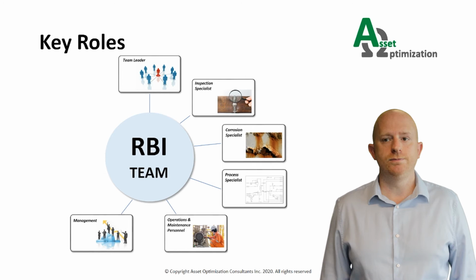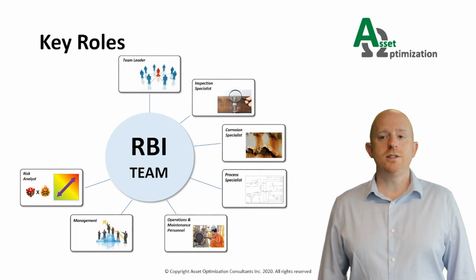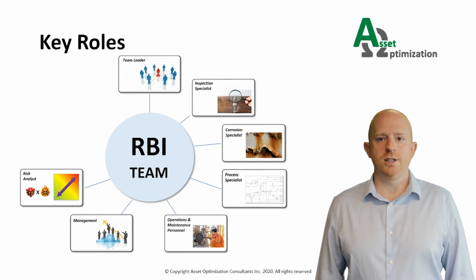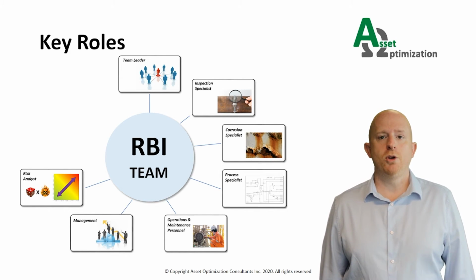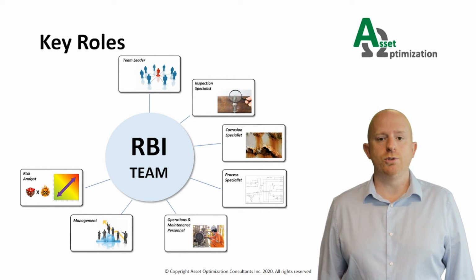The risk analyst is responsible for collating the requisite data provided by the team members and performing the risk analysis. The individual or individuals may be a specialist in this area or may well be one of the other team members. Typically, the risk analyst will be responsible for defining the required data based upon the risk analysis methodology, defining the accuracy levels for the data, verifying data quality and the basis of the assumptions, data input or transfer to the RBI software if the RBI software is being used and running the RBI software program, or manually calculating risk if no software is being used, communicating the risk outputs in an understandable way and producing reports.